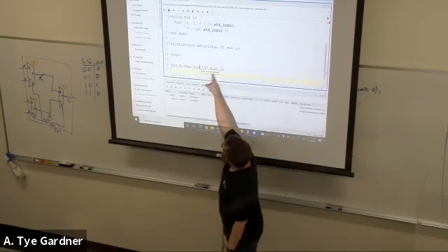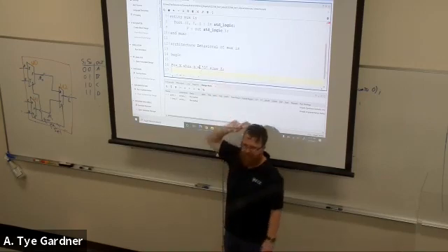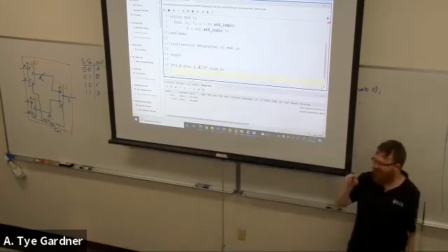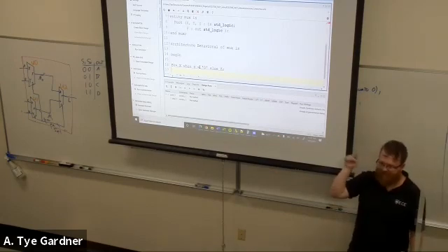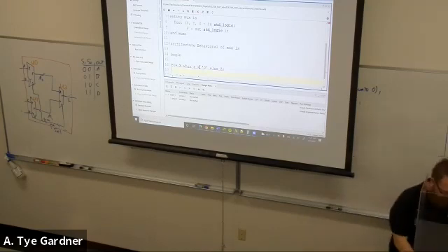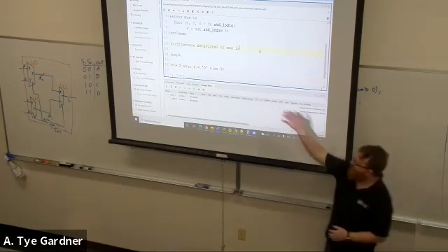Notice that this is a little z, I wrote a big Z, it's because VHDL is not case sensitive. Be careful with that, because you can't declare something little z and then something else big Z, they'll be the same signal. So Z is not helpful, I'm gonna make it Y. Control S saves it, I have now designed a mux.